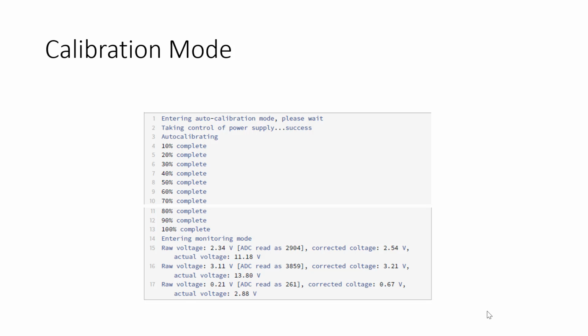So half a second, and then there's, what do we say, 300? Roughly, yeah. So it's going to take about 2 minutes. So we're looking at about 2.5 minutes for this process to complete at 500 milliseconds per step. For the sake of testing, you could take fewer steps. Oh, sorry, that was for a 50 millivolt step. It's going to be 300. Yeah. So we're looking at 5 minutes. It should take about 5 minutes to do the calibration then, right? At 50 millivolts and 500 milliseconds.